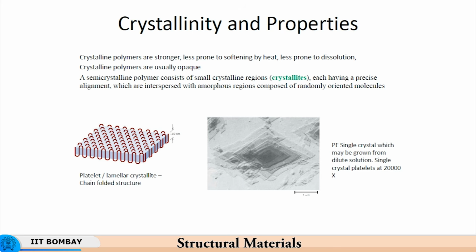So in the regions where greater strength and greater stiffness of the basket are required, you would allow the polymer to crystallize there, because you need more strength and less propensity to soften or get attacked by chemicals.